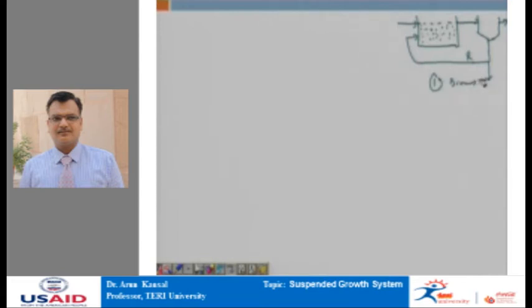The second question, which is important, is that the BOD coming in the wastewater is never constant, because sewage or any industrial wastewater always fluctuates in any of its characteristic parameters. So because of the fluctuation in the concentration, how can we ensure that the BOD in the treated effluent is less than 30 milligrams per liter? So this is the second question, that is, self-regulation of the system. We will understand how these two concepts work simultaneously.